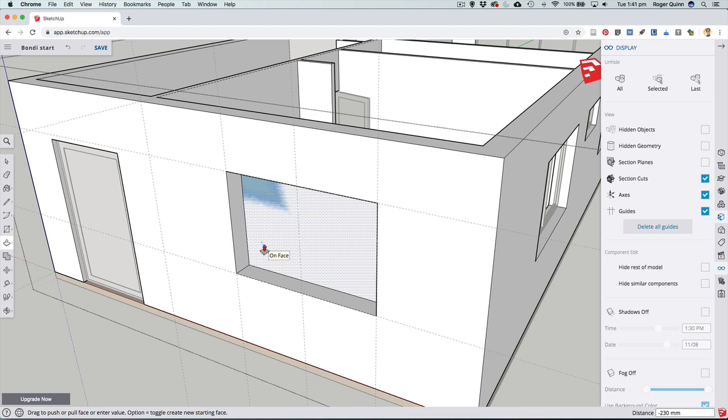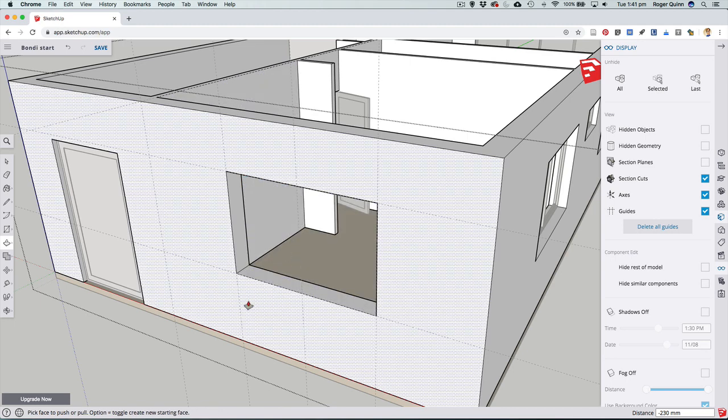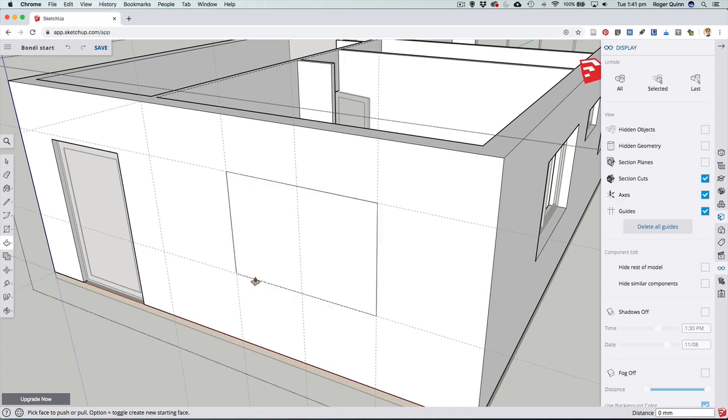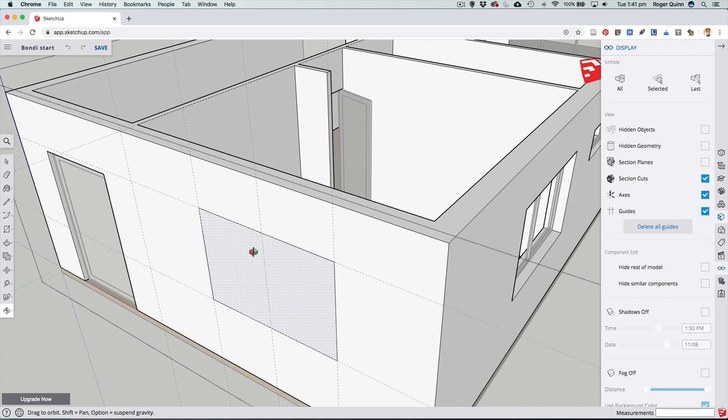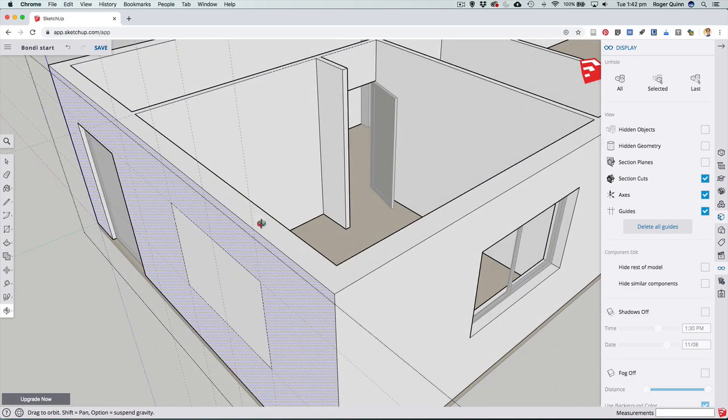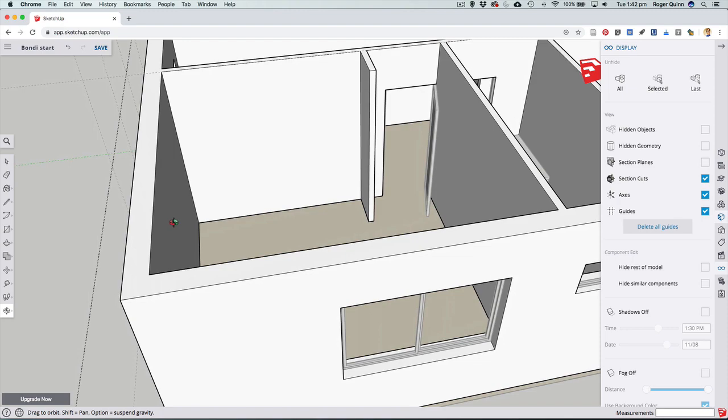Now, if you have any problems with getting it to knock a hole like that, because it should work just by pushing it all the way through, a tip for that, if it's being troublesome, is when you go to push-pull that, to start to push-pull, and then as you've got your mouse held in, just go up and touch that inside edge there, because in this case that's going to represent the other side of that face. Again, just to show what we're doing here, I'm trying to push-pull that to go all the way through to this inside wall and knock it out, right?